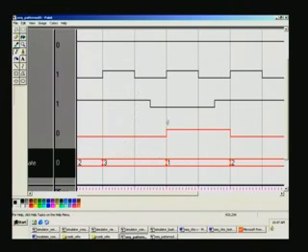Then only it will go into the next one, and only after touching this, although it is changing here, the processing actually takes place only at this point of time, right? As far as the output is concerned, because the output is also dependent upon the positive edge of the clock. Always at positive edge of the clock in state S3, you set that particular output, right? It says here. So that means it can take place only after 1 clock delay. Are you clear?